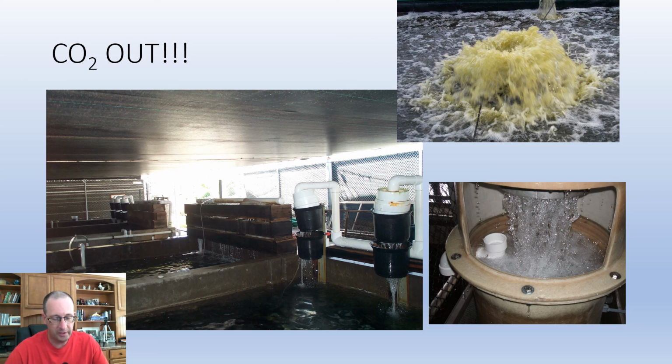If you really wanted to do something to add to this and make it a little bit more high-tech, you might be able to actually build such a column where it had an exhaust fan blowing out of the top of the column, kind of like a chimney effect as you rained water through the column. I've seen that done once or twice on some systems to the point that it actually changed the water chemistry quite a bit. Not only did they pull the CO2 out very quickly, but it actually helped this particular lab get around an iron problem that they had in their water.